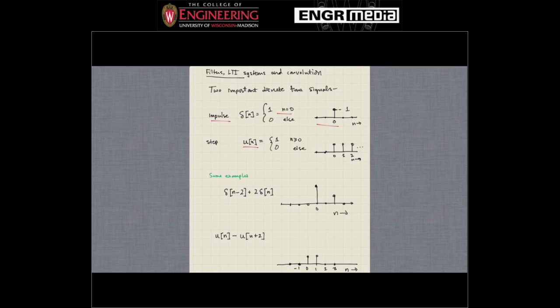That's just drawn on the right here. It just looks like a step function. So at 0, you can think of it as turning on, and it just stays on with a value of 1 for any n greater than or equal to 0. So even at 0, it takes on the value of +1. But of course, at time n equals -1, it's just 0.